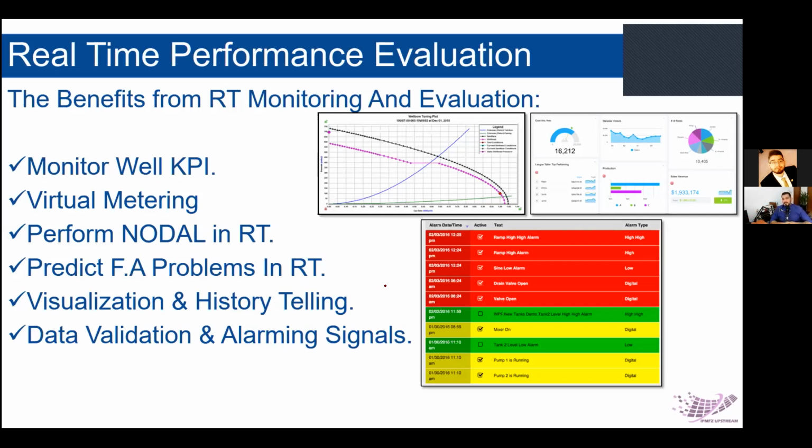What you do is connect transmitters to the gauges, and then send that data over sea or over land using a wireless connection. Then you monitor the same parameters we talked about, but this time in real time. The real time gives you an advantage. You will find the problem before it becomes bigger and out of hand. Plus, you can utilize these nifty warning signs.